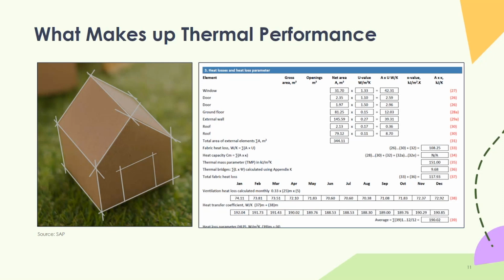heat transfer coefficient. And so when I refer to measuring a heat transfer coefficient, you can measure that number directly in situ within a building. And from that, you've essentially bypassed all of these assumptions around thermal bridging and assuming U values for each individual element. Thermal bridging is something that's really difficult to otherwise model or calculate. And so by jumping straight in and measuring the headline HTC, you've bypassed all the risks around assumptions here, or at least been able to then help calibrate, sort of backwards calibrate, your model.